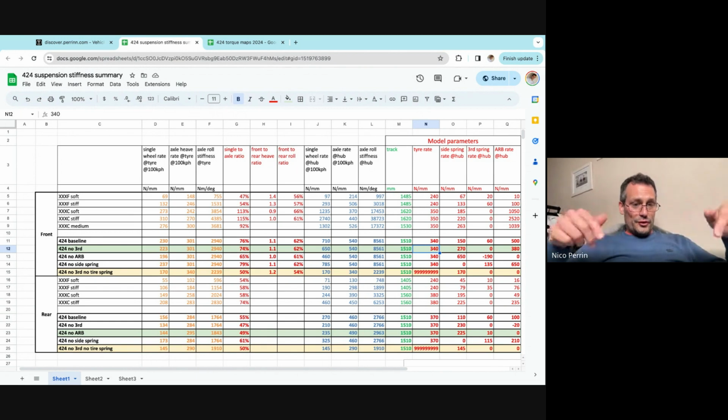So when you do that, you rely more on one tire to produce your lateral force, and your overall axle potential has dropped. Instead of having 2 tires evenly loaded to produce your lateral load, you rely more just on one tire. And we've seen before that as you press more on one tire, you saturate it and your grip is dropping.